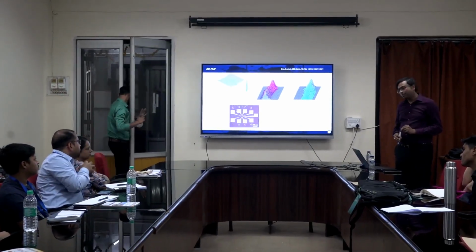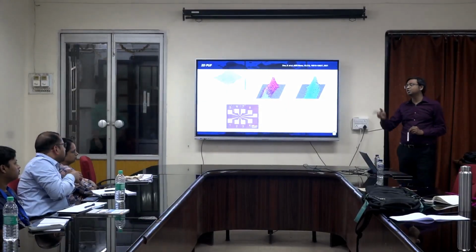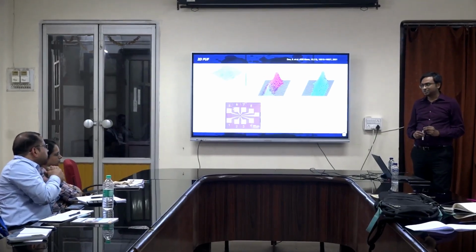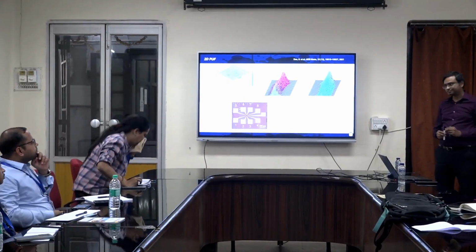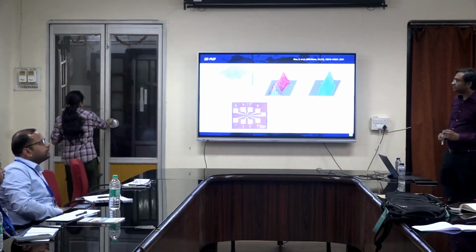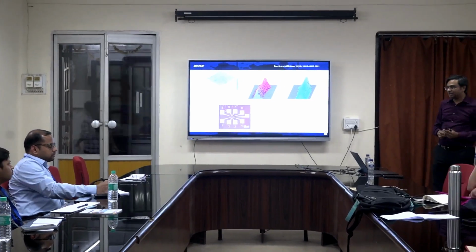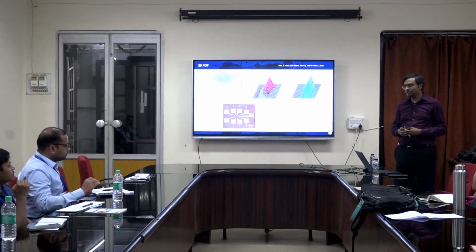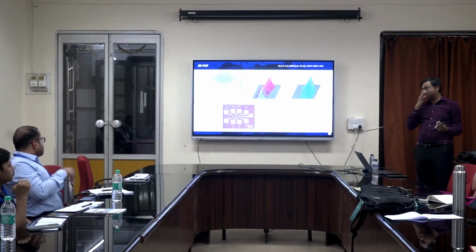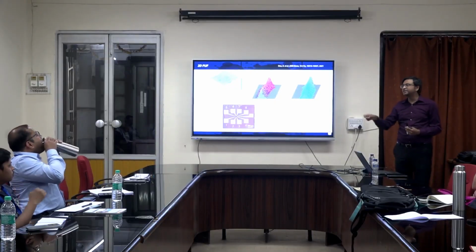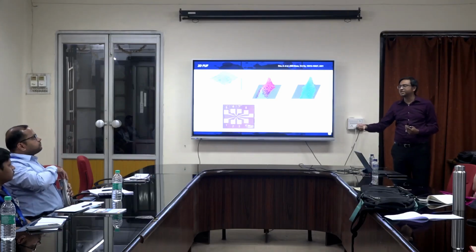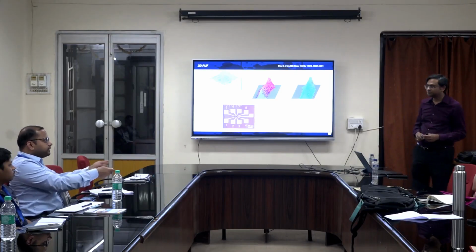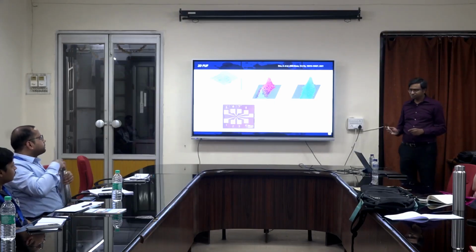Could be good, yes. Optical would be easier, it is just that it has to work through your packaging, because the packaging material is often not transparent. Correct. Agreed. I mean, there are pros and cons in both aspects. I think whenever you put the chip on a printed circuit board, you have access to the IV characteristics of the chip. It is much simpler to do it using IV than using optical methods. Because at the end of the day, it will be integrated into some circuit, right? And you need to simply write a code to first check whether it's an authenticated chip or not. Possible, yeah. Okay, this part is good, right?